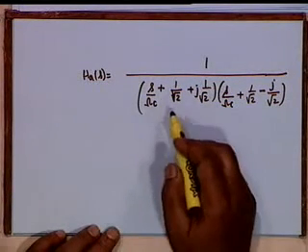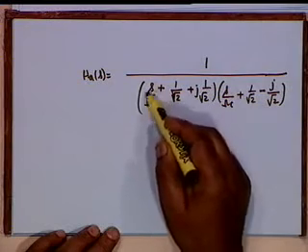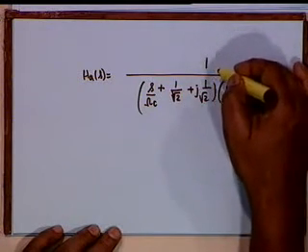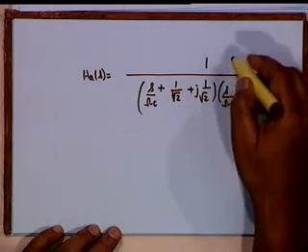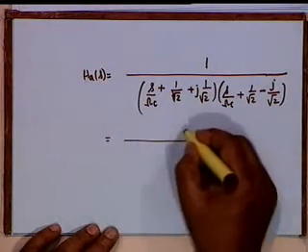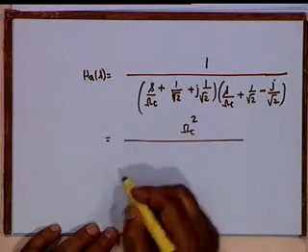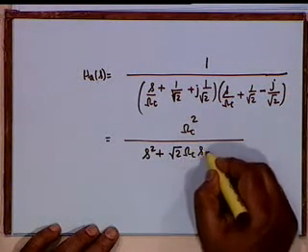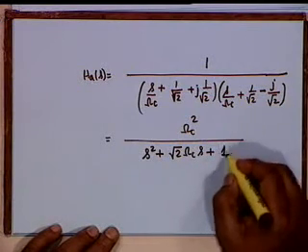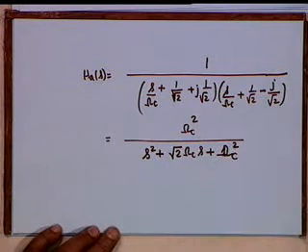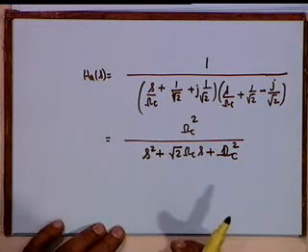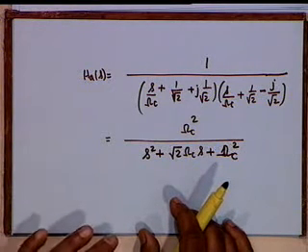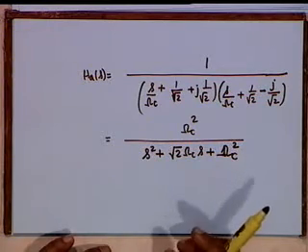We have written the transfer function in terms of s by omega c, otherwise we will have to multiply this by omega c, and the numerator we shall have to use omega c squared, and if you multiply this out, what you will get is omega c squared in the numerator and s squared plus root 2 omega c s plus omega c squared in the denominator. So the denominator of H_A of s is called a Butterworth polynomial.